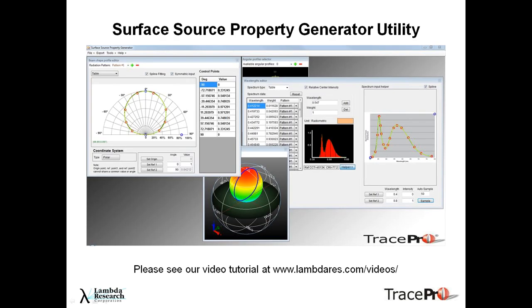First is the Surface Source Property Generator utility. This utility lets us take a beam pattern and a spectrum right from a data sheet, whether it's an LED data sheet or any lighting manufacturer data sheet, and we cut and paste those graphs for the spectrum and for the beam pattern into this utility, and we basically click on the curve to trace that curve. The more clicks we do, the closer we can follow the curve.